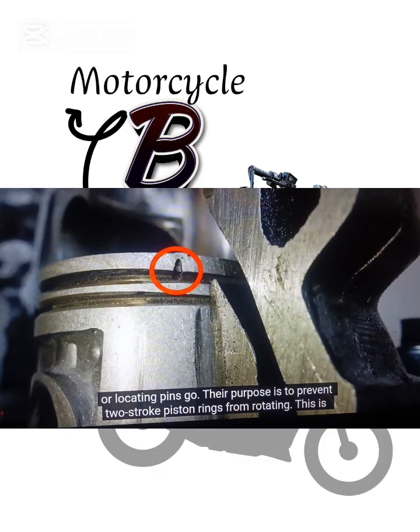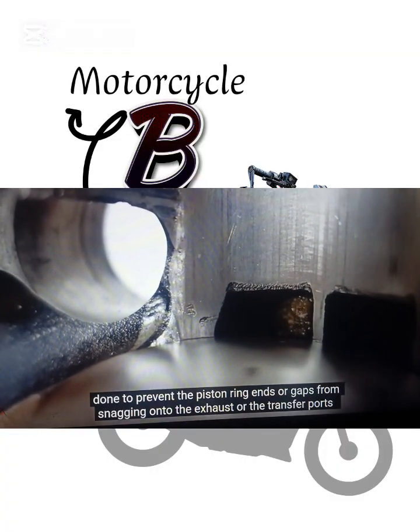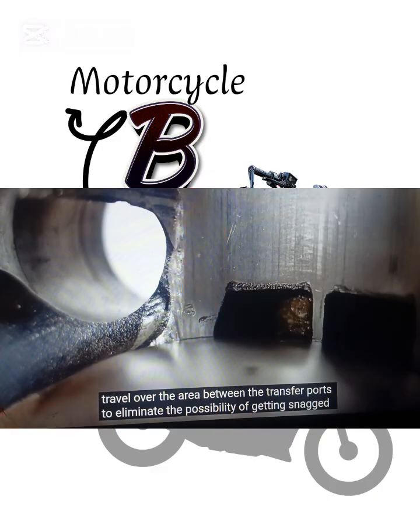Their purpose is to prevent two-stroke piston rings from rotating. This is done to prevent the piston ring ends or gaps from snagging onto the exhaust or the transfer ports, which would lead to engine failure. Instead, the rings are fixed to ensure that the gaps always travel over the area between the transfer ports to eliminate the possibility of getting snagged by the ports.